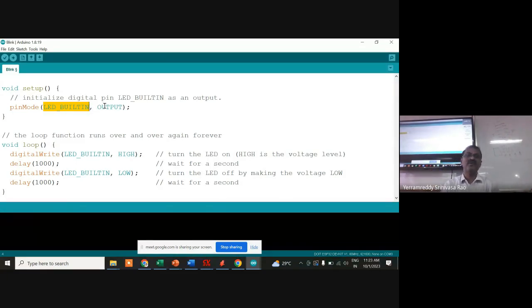उसको हमने कॉन्फ़िगर किया आउटपुट, बिकॉज एलईडी इज आउटपुट. फिर इनफाइनाइट लूप में हमने क्या लिखा है? डिजिटल राइट मीन्स एज आई सेड कि वी वांट टू राइट द डेटा. किसको राइट करना है? एलईडी बिल्ट इन को. कौन सा वैल्यू राइट करना है? हाई. देन डिले, बिकॉज वी वांट टू पुट वेट फॉर सम टाइम ऑन टाइम. फिर एलईडी बिल्ट इन को लो करना है, फिर डिले. अंडरस्टूड दिस प्रोग्राम? एनी डाउट्स?